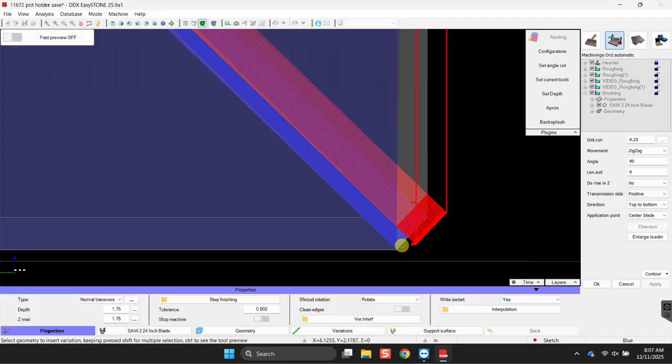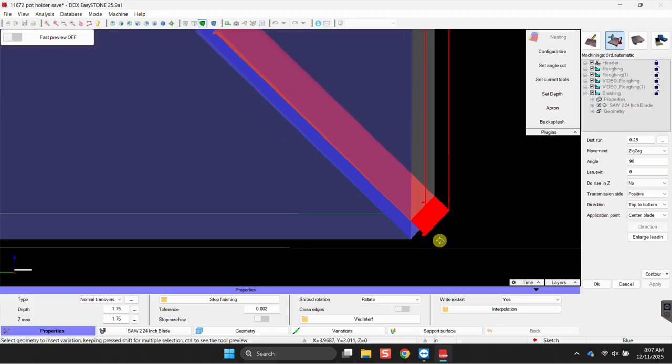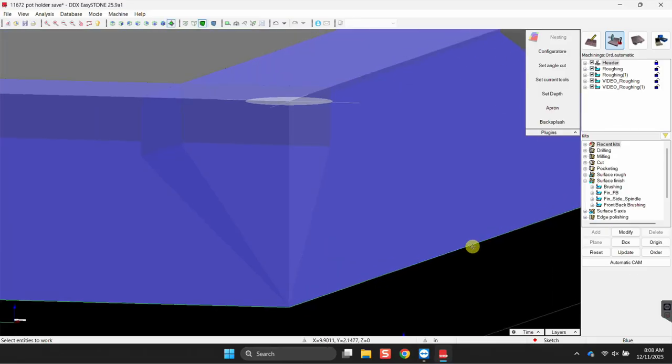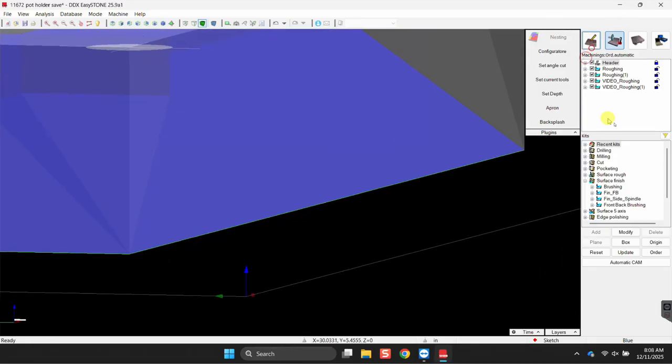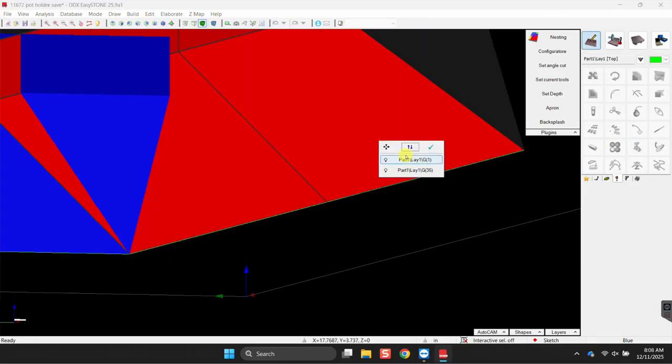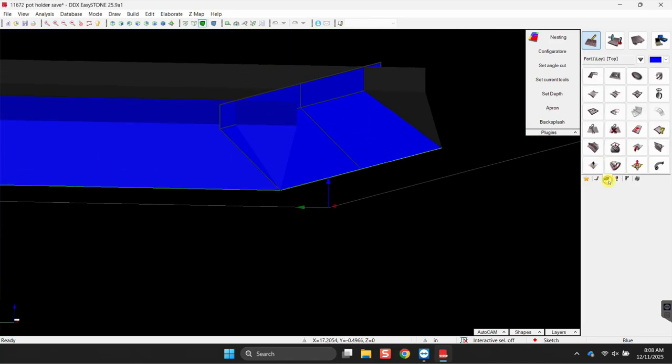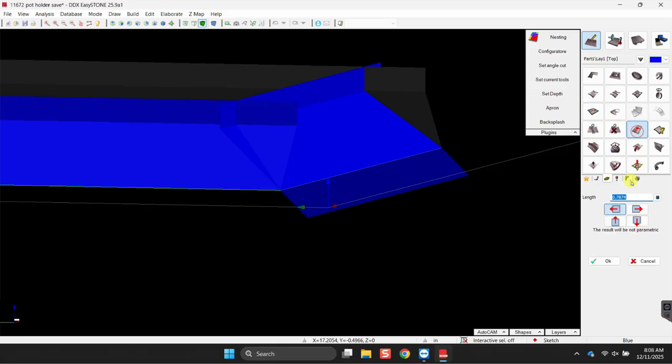Now, with this being said, there's a couple different ways around this. One is messing with the zone, right? I've seen that a lot. The other, I don't know if it's video worthy, we could play around with it. If I come back to the draw tab and I click on this guy, let's go here to build. There's one, where is it? Oh, enlarge surfaces, right? So right here, I can enlarge this to force the brushing to come out further. But I don't need a lot.